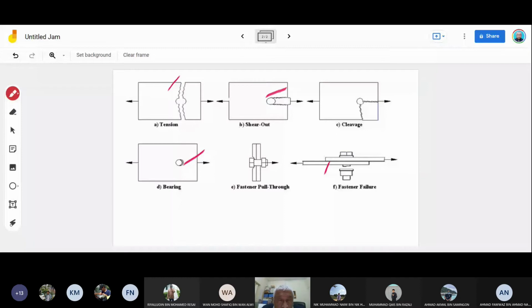If you still have a very thick one and you're not sorting it out by the alternative given by the OEM through the manual, then that's already a violation. That's already a problem in the design. So that's why I didn't go really into rivet bending and things like that, because if you refer to the manual when doing the design, you may not get into that situation. However, tension, shear out, bearing and fastener shear, those are very common.